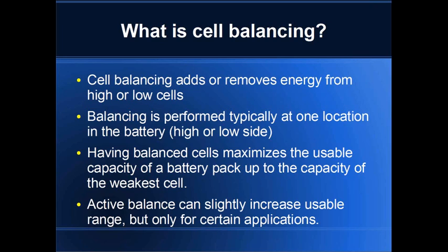There are certain applications where you may want to bottom balance if you're maybe spending more time near the bottom. Hybrid vehicles, for example, is a little bit more tricky because you don't have a charger in those, and so the state of charge ends up resting at whatever it rests at when somebody parks the car. So with a hybrid application, you may need to pick a certain state of charge window, and if the car happens to be parked in that particular window, then it can do balancing, and it just waits for the next time that it's within that range.